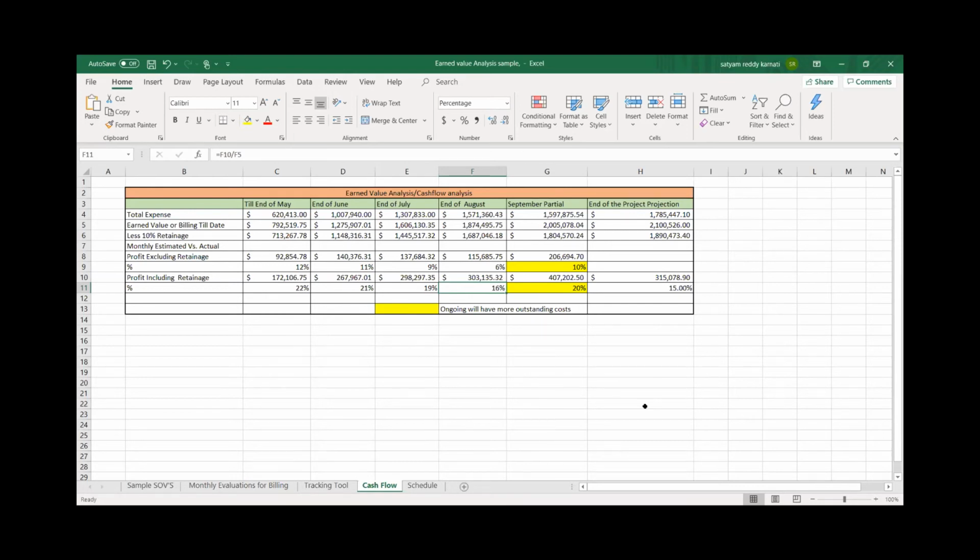When I estimated, what we do is we put a crew together. I have two carpenters, three laborers, one operator, and certain equipment, and they are going to do 110 linear feet a day. That's my initial thought as an estimator. We share that thought with our foreman. He's going to say, "Oh, you screwed it up," or "Yeah, that works."